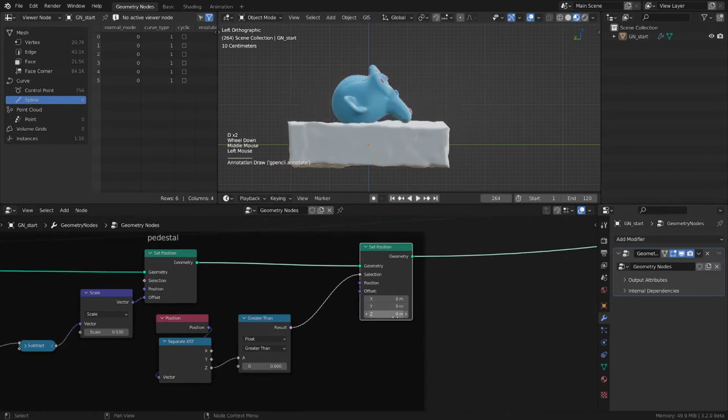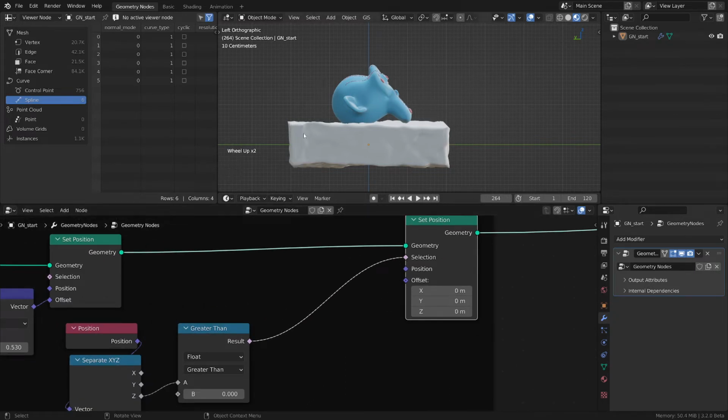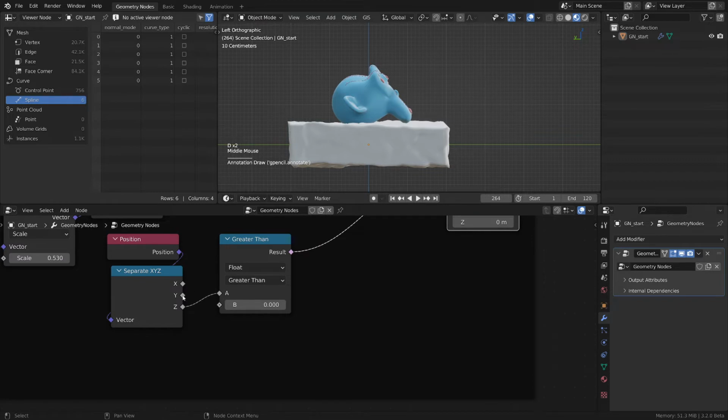So we can cancel this value because we will do a special deformation. We have a selection for Boolean, meaning a point is either selected or not. So the idea is, how can we make a gradual change like that in the geometry? How can we make a mask that has a fall off, basically? This is the cool part that we want to do. Well, let's think. We want to modify the height value based on the position on the y value here. So we want to modify the z value based on information from the y value. So we have to do something with this y value.